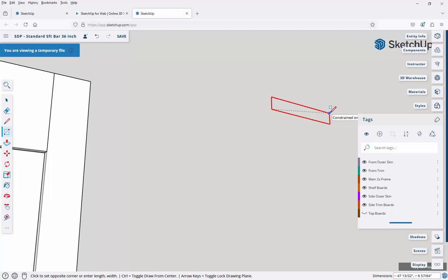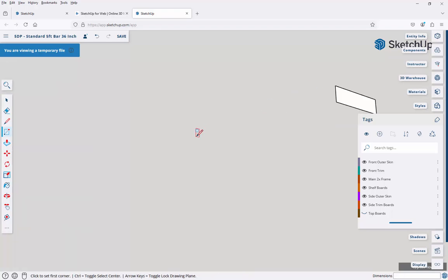The big number is first, and then the little number. And that's important. When we enter in how big we want our rectangle to be, we want to enter it in that format. So in other words, my big dimension here is 6, and my little dimension here is 1.5. So I hit 6 comma 1.5, and you can see I get this little tiny rectangle out here in space.